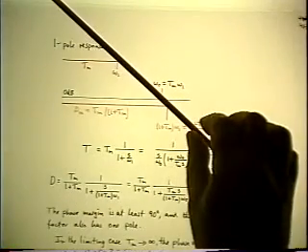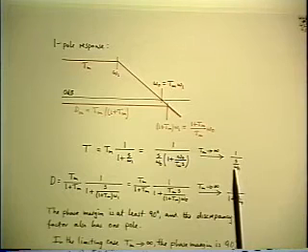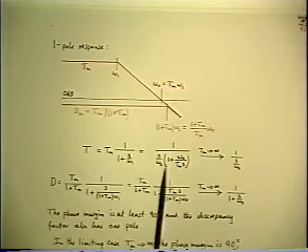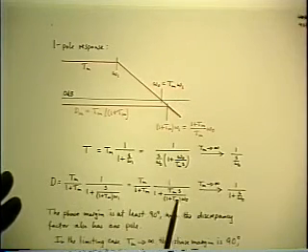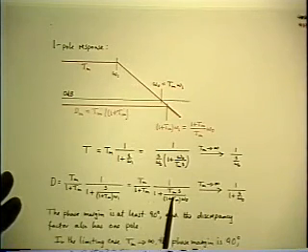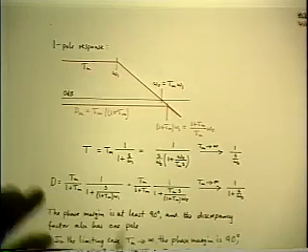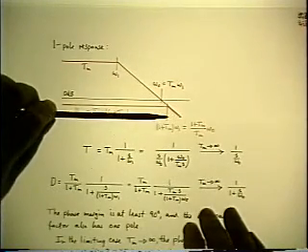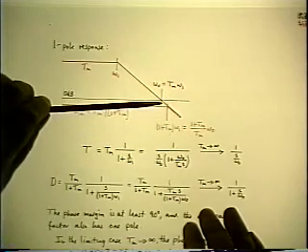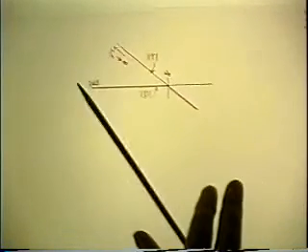which is this single slope with unity magnitude at the frequency omega 0, which we've already done several times as well. At the same time, rewrite D to get rid of omega 1, and then let Tm go to infinity in that one, and you get 1 over 1 plus S over omega 0, which means that D has approached 0 dB and its corner frequency has approached omega 0. So the whole thing comes down to that.